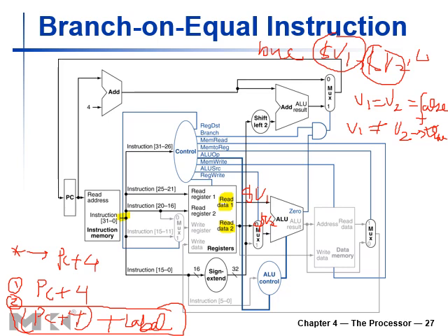Now in this particular scenario, we have a branch signal. Definitely this signal will go high if there is a branch instruction, either branch equal or branch not equal. But now the zero flag will decide what happens. If we have the same circuit as branch equal, then for branch not equal the condition is reversed, and we are operating in the reverse direction. So what we have to do is invert this zero flag, and we have used an inverter, a NOT gate, here.